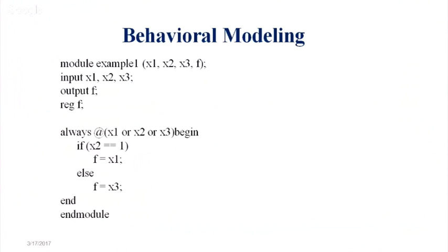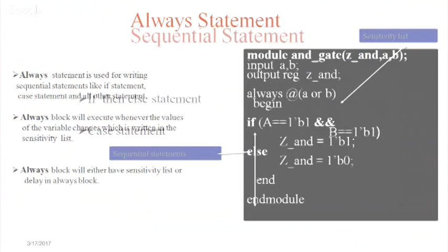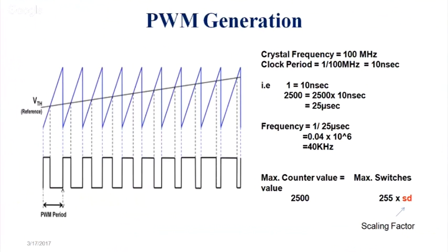We have basic knowledge of FPGA, and we were talking about behavioral modeling of the Verilog language. Now we just move on further. I have told you about PWM generation, and I am just going to focus on this major area. For a PWM, we have to make a counter which will start from an initial value and go to some predefined value, and in between we put a threshold value so that we can produce different types of PWM wave. How we will do it in FPGA, or in Verilog, I will show you.